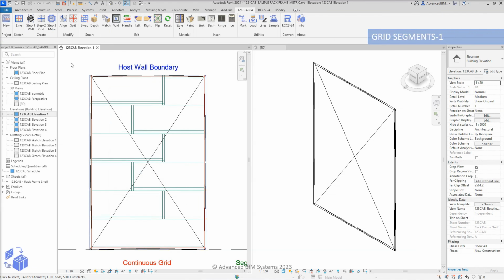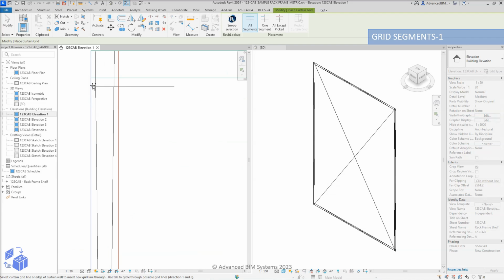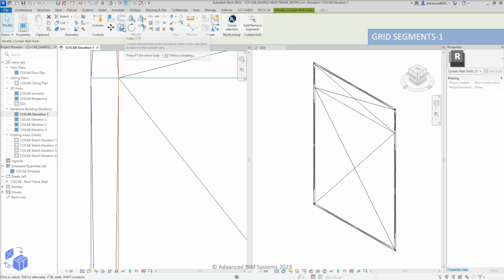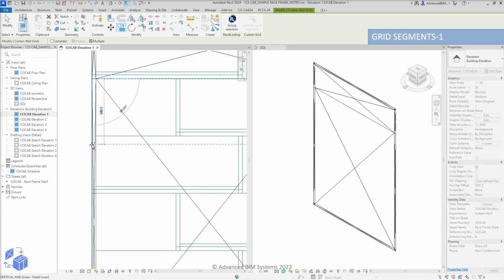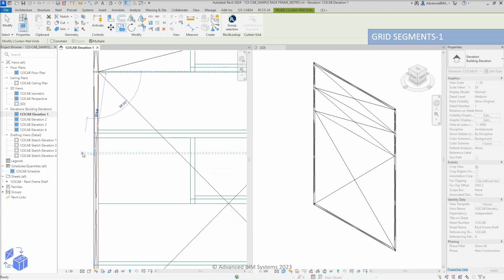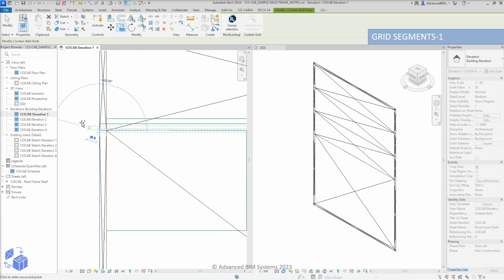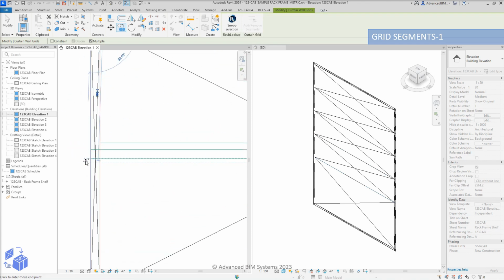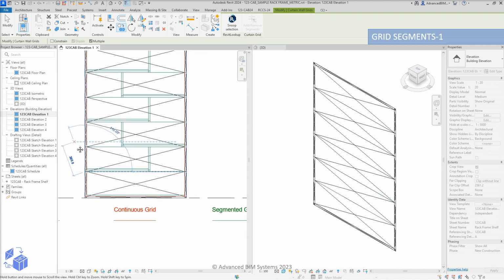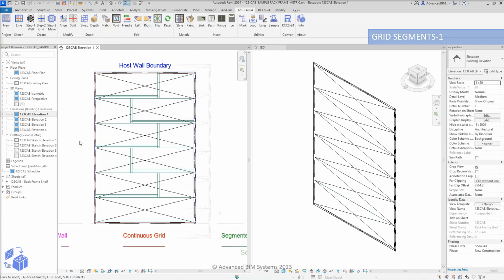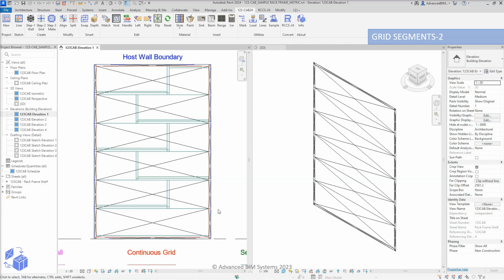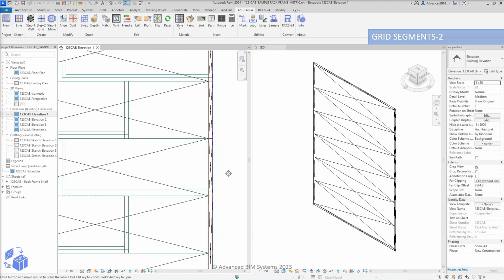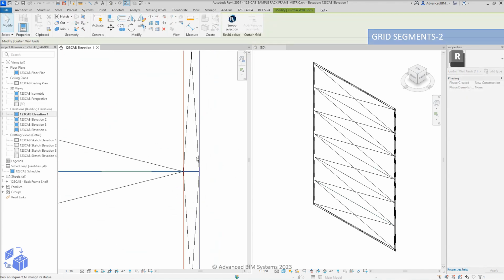The next step is to place the horizontal grids that will make up the lower part of the horizontal space frame. In most cases, it's possible to place a single grid, which can then be copied multiple times throughout the design. Now, let's use the Add Remove Segments tool to remove any leftover segments from the newly placed horizontal grids.